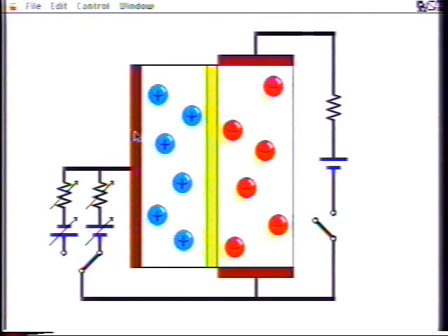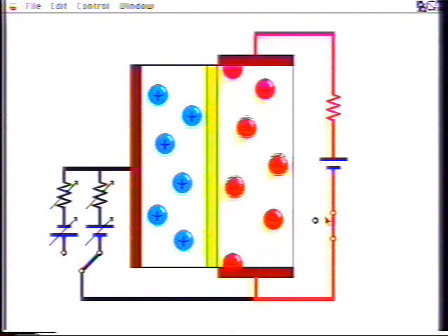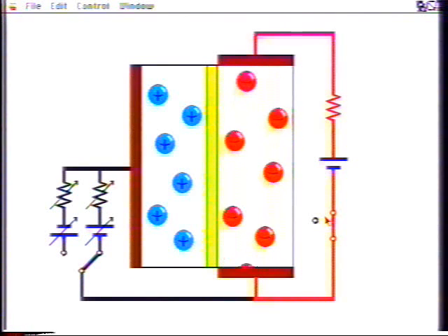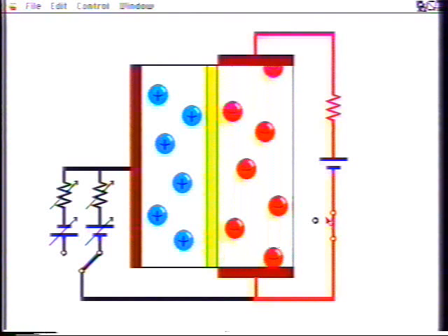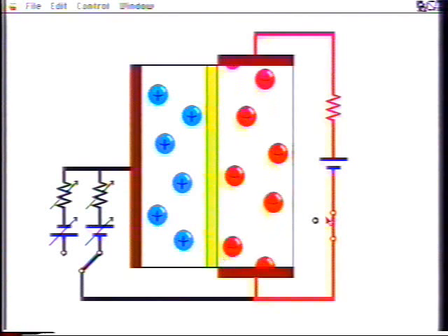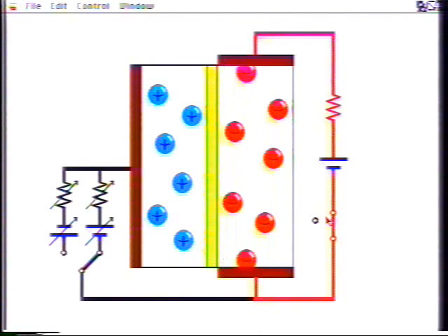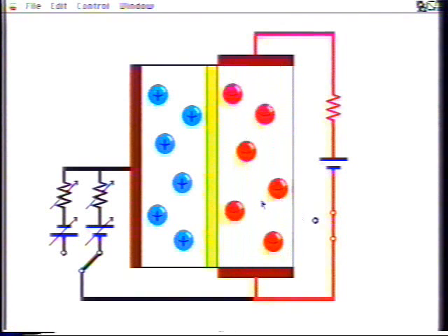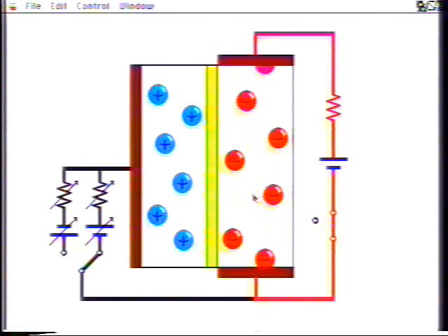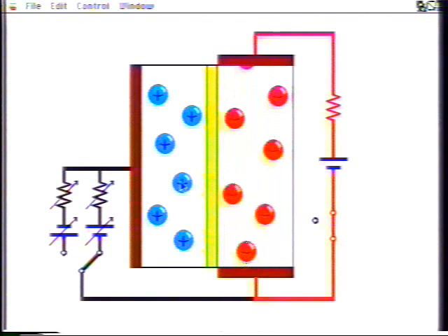There are now mobile electrons available in the channel so that, when the drain circuit is closed, current flows in the output circuit. The basic charge control relation applies. The output current is the total charge in transit divided by the mean transit time. However, the charge in transit is equal, in magnitude, to the amount of charge that was placed on the gate.